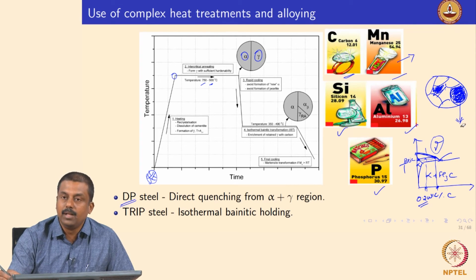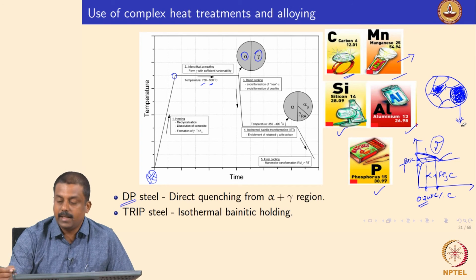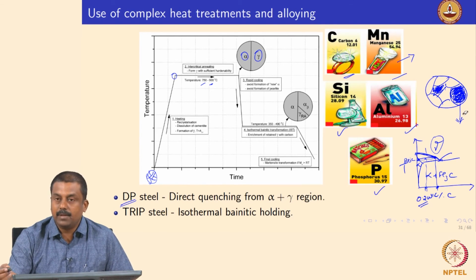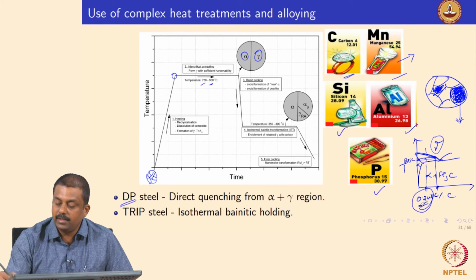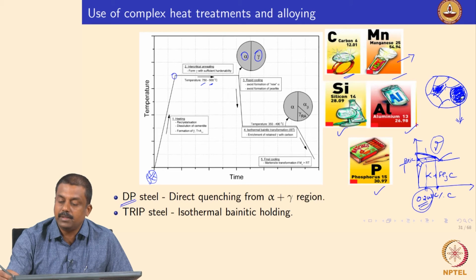When you subsequently cool to room temperature, the austenite transforms into martensite. The cooling rate is dictated by your process, but with a high carbon concentration, even a significantly lower cooling rate than for austenite containing only 0.2 weight% carbon can achieve the martensitic transformation.